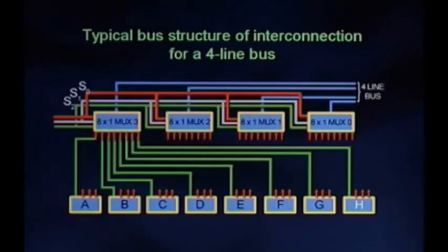A bus structure constructed with multiplexers requires a large number of multiplexers and hence is felt to be inconvenient in some applications. An alternative approach is to use a special type of logic devices called tri-state buffers at the output of each signal, which have 3 stable states. Many standard logic functions are also available as tri-state logic devices.